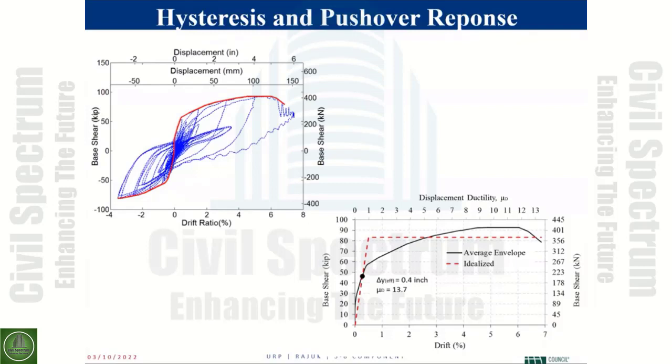There we began to fracture some of the bars. The bars here were conventional steel bars. And you see, if you look at the right side of the figure, I'm not sure if you can see my cursor, but in this area, that's where we began to fracture some of the bars. And of course, the capacity, the force began to drop.